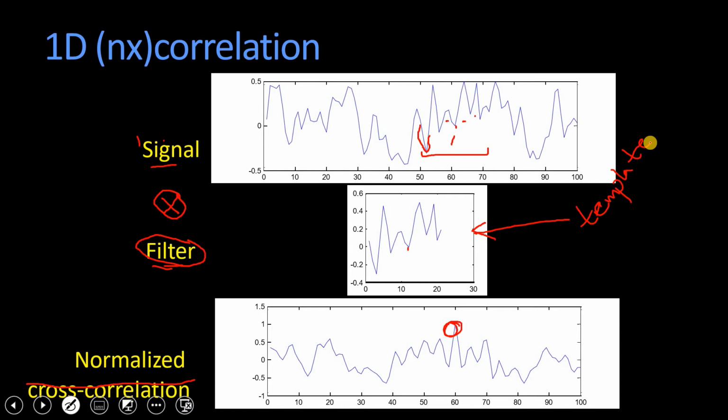We try to match a shorter signal in a broader main signal, and what we do is nothing complicated. We only take the smaller signal, the template, apply correlation between these two signals, and the result will have the peak value where the template matches. Clear? Now we will apply the same thing on the image.